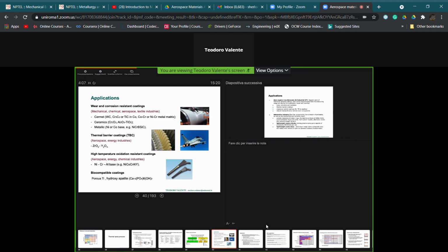The phase which is going to be melted in order to fabricate the coating is the metallic matrix, and thus the ceramic particles still remain solid and are distributed inside the coatings after coating fabrication, due to the fact that we have a liquid phase which is represented by the metallic matrix.